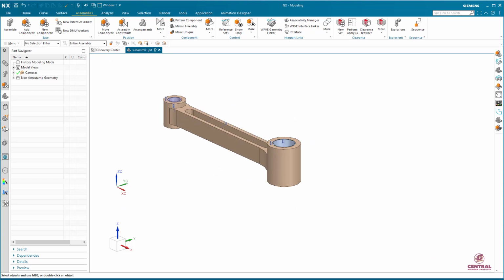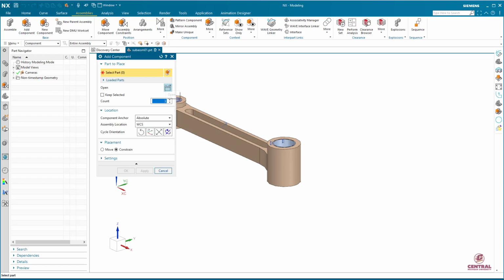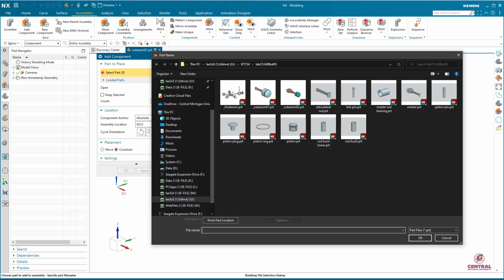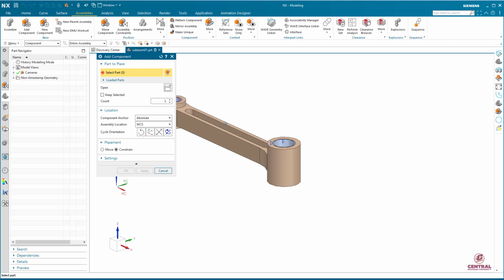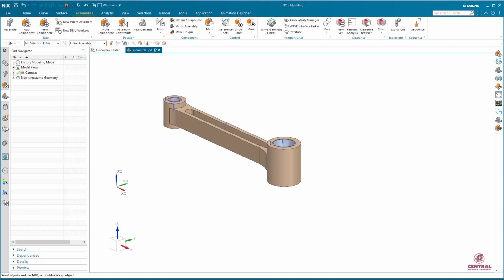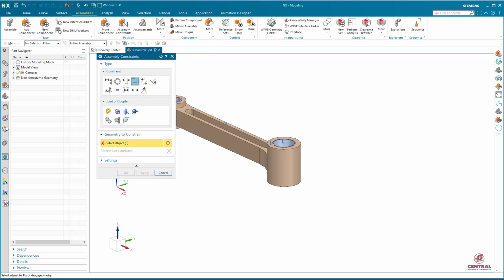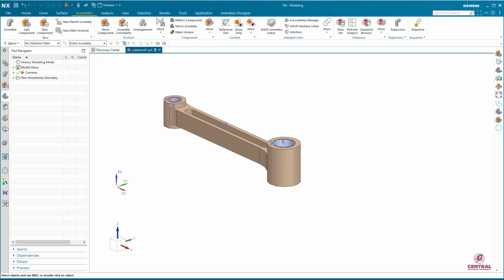So pretty good. Probably you find it yourself, it's going way faster than the previous assignment you did, because we are using add component. At the same time we are editing, right? We are editing a move or constraining at the same time within just add component. But everyone already knows that. Later, if you need to add more constraints, you can simply go to assembly constraint. You can add additional assembly constraints.